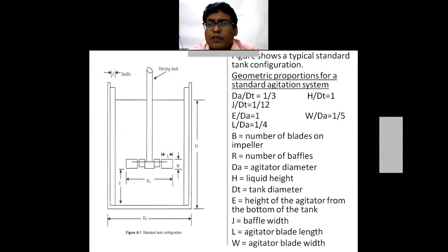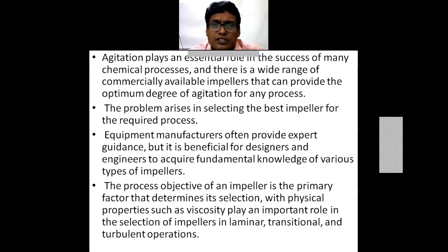It's a standard general configuration, but again it depends on the type of impeller. If it's a propeller type or a paddle type, then these configurations are okay. Now, if it is an anchor type, then a different configuration has to be taken into consideration. So which type of impeller we are using is most important, and which geometric proportions have to be taken into consideration for the stirred tank vessels.